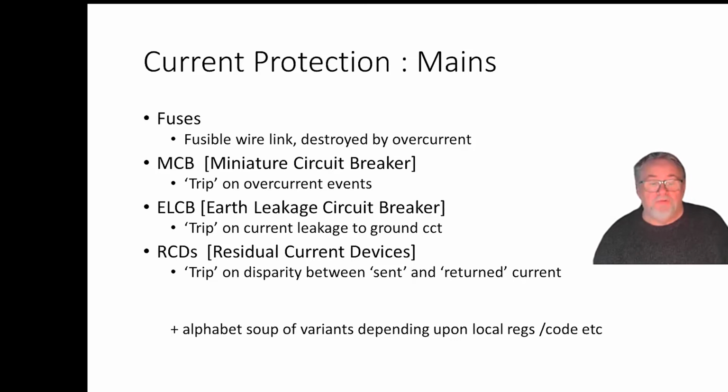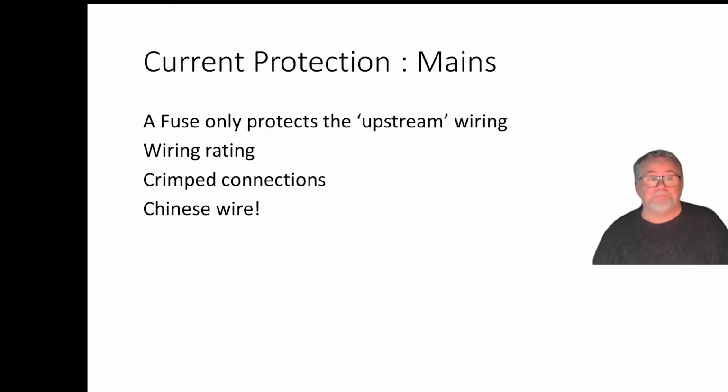We do all know about fuses though. A fuse protects the wiring upstream of the fuse. If you put a fuse in a circuit, it is only there to protect the wiring that is upstream of where you just put the fuse. You should know about wiring ratings. Every piece of wire has a rating, a maximum current which you should not exceed.